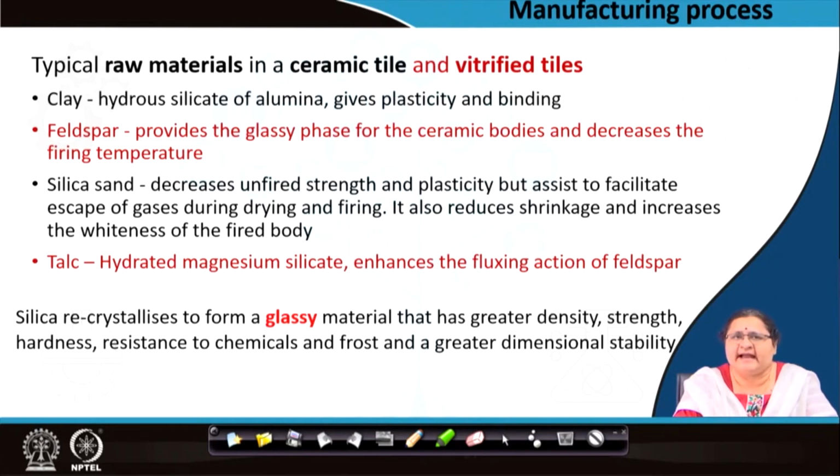and silica sand decreases the unfired strength and the plasticity, but facilitates the escape of gases, the fumes which arise due to the reactions when the process is on, when it is in the furnace. It reduces shrinkage and increases the whiteness of the fired body.